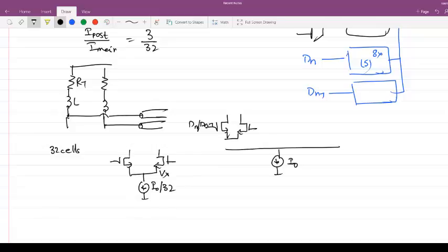If you say that Dn is a different voltage and Dn minus 1 is a different voltage, fine, that is right. But here Dn and Dn minus 1 are digital signals with the same signal pattern. The only thing is these are differential, meaning Dn can be 1, Dn minus 1 can be 0, but in that case you are having a differential signal, so that will not create any difference in the Vx node to the extent that these cells are matched. Mismatch is a different case.